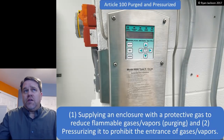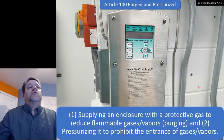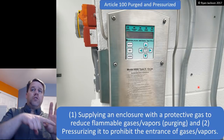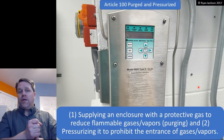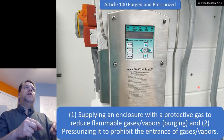Purging and pressurizing, again, is defined in Article 100, and that's supplying an enclosure with a protective gas to reduce the flammable gases or vapors, and that's the purging part of it. So it's a two-part approach. Number one, you purge the equipment. You supply gas, and you get rid of all of the flammable gases that are inside the equipment, right? You purge it. So you might use nitrogen.